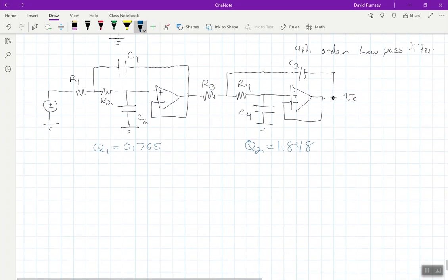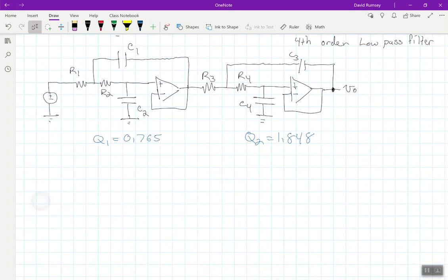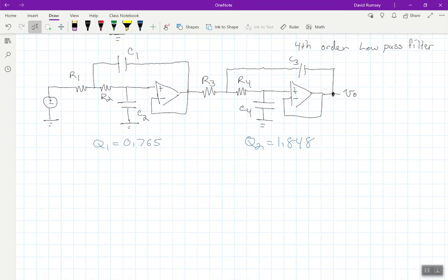Now, the way Byers teaches us how to do filter design is slightly different than what we're doing here, because we're deciding what the cutoff frequency is, as opposed to there's this WP and WS, because there's this trade-off between order and how steep you can make this. We're just making fourth orders with a particular cutoff frequency. So I'm just going to arbitrarily choose my 3 dB frequency to be 1 kilohertz.